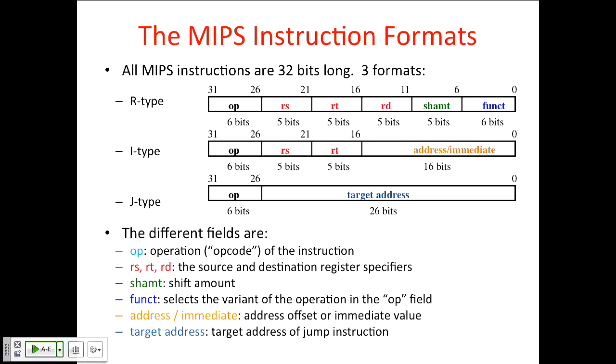If you notice in the MIPS encoding, there's one opcode that's used for a whole bunch of different ALU operations because they have space at the bottom to use this function field to tell you which of those operations you should do. So the opcode tells you it's a register ALU operation, and these low 6 bits in the funct field tell you whether it's an add or a subtract or an XOR or an AND when you're doing register operations. When you're doing register immediate, the I type, the immediate occupies all these bits. So now you need different opcodes for an add and a subtract in the MIPS encoding, right? They try to use the minimum number of bits, but they have to be a little bit clever in how they encode those in various fields. So these instruction formats are what the hardware has to look at to decode an instruction.